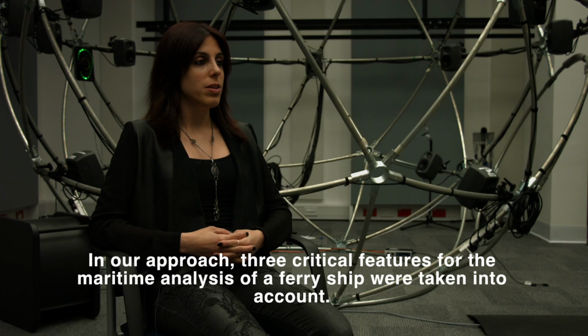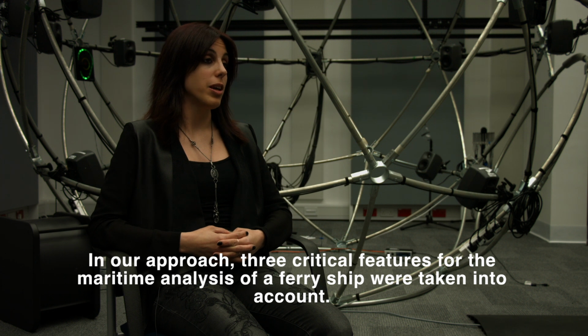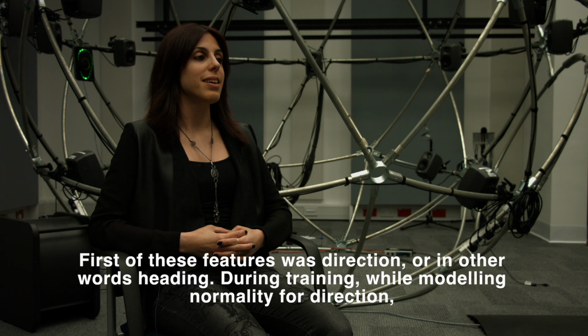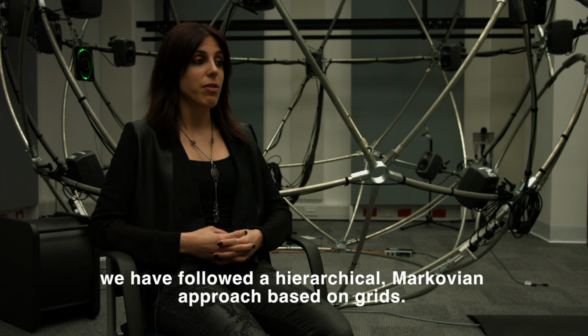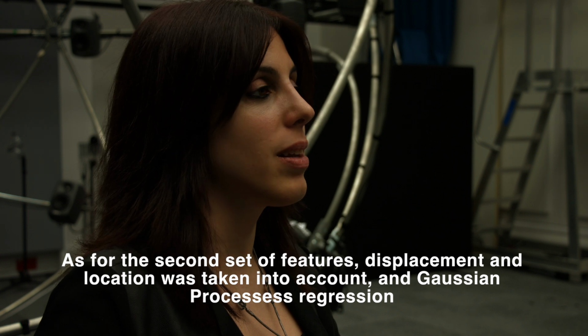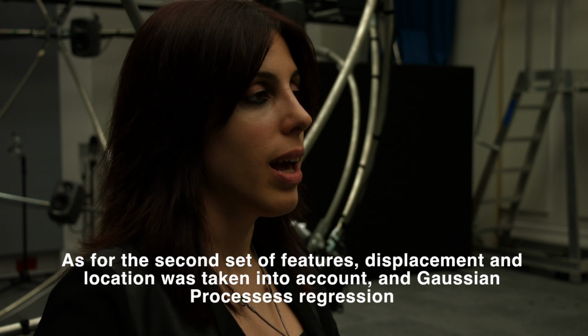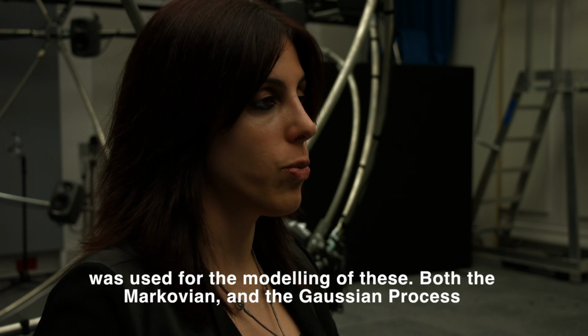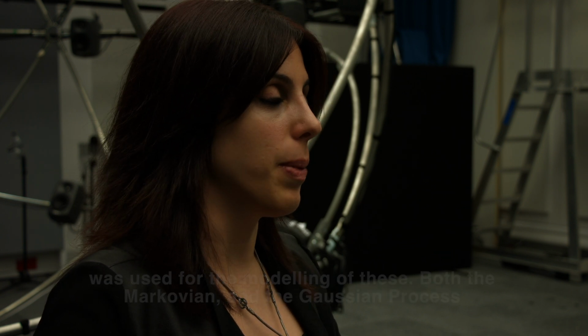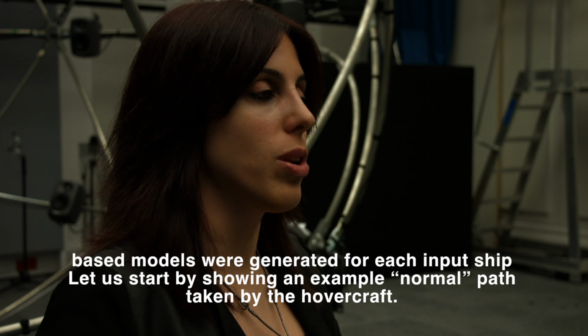In our approach, three critical features for the maritime analysis of a ferry ship were taken into account. First of these features was direction, or in other words, heading. During training, while modeling normality for direction, we have followed a hierarchical Markovian approach based on grids. As for the second set of features, displacement and location was taken into account, and Gaussian process regression was used for the modeling of these.